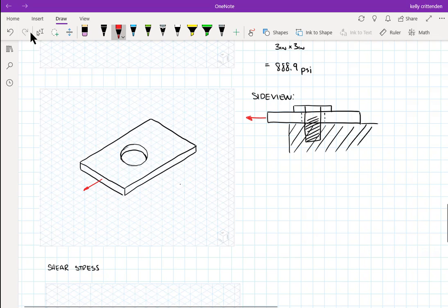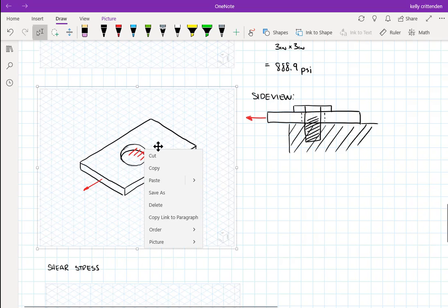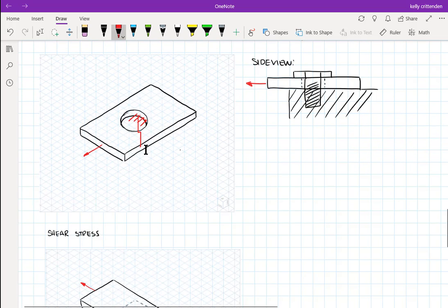So what ends up happening, if there's a bolt in that hole, and the bolt is, again, indestructible, we're not worried about it right now, I am forcing only half of this hole to support all this force. You know, this half of the hole is supporting the force. Let's make it 10,000 pounds. So all of this added together over here is 10,000 pounds.